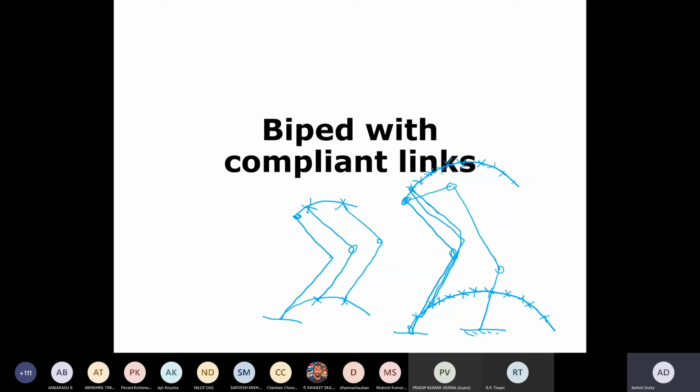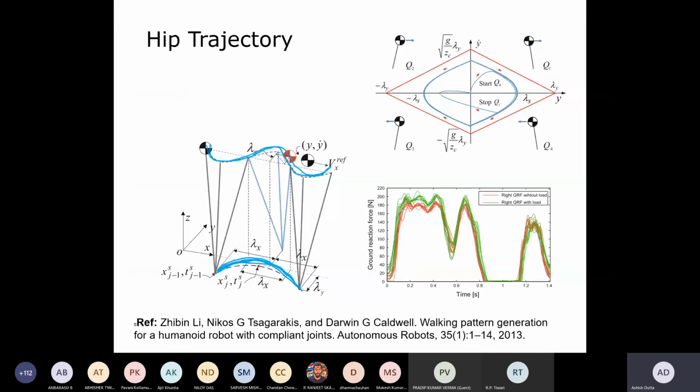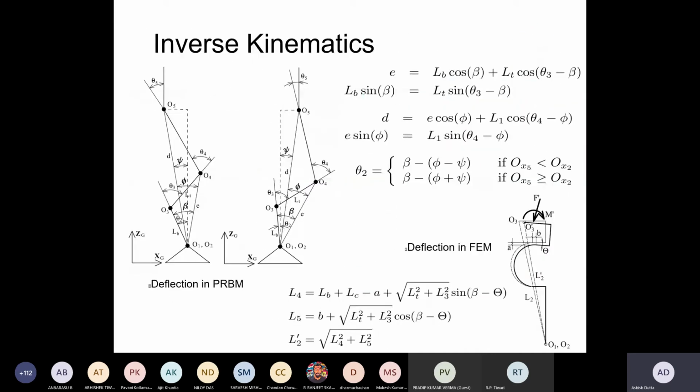And if you look at this, this is a two-link system. And you know the inverse kinematics of a two-link system. So from geometry, we can solve this very easily. Okay, so it is 8 degrees of freedom or 16 degrees of freedom. It looks very complicated in terms of inverse kinematics, but actually it's not. Why? Because if you're looking at the hip trajectory and the leg trajectory, in between the hip and the leg there are the legs, which is basically a two-link system. So you can very easily solve this from geometry itself. Okay, so this is the geometrical solution. This is my two-link system. This is the hip trajectory, this is the leg trajectory, two links. So you know what is this angle, you know what is that angle. From geometry, it's very easy to get that. Okay, so although it looks difficult, it's not.